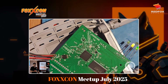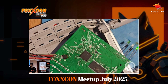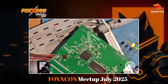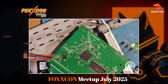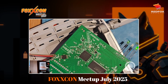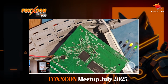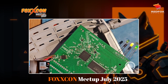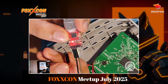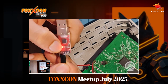Here it will, so I will be ignoring the power pin and I'll just be connecting the rest of the 3 pins, because of the mentioned fact. So I'll ignore the first one. I'll connect the ground to ground. I'll connect the transmit pin TX to our RX. I'll connect the transmit pin to the receive here.